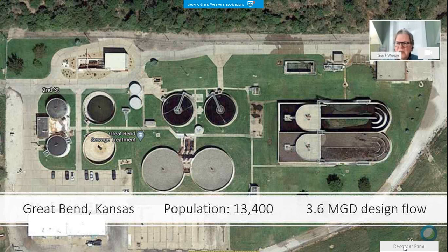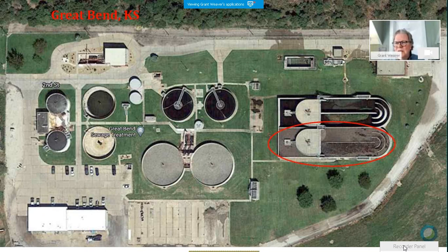The folks there did exactly what we're talking about. They put a variable frequency drive on their rotor for their oxidation ditch so they could run that speed just right to get ammonia removal, which in this case is the bottom, the turbulent part that's going from left to right, and then the top part is anoxic, low enough oxygen. It took them several months to dial that in and get the right settings. There was a DO feedback that is controlling the speed.